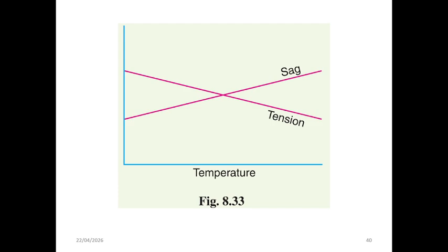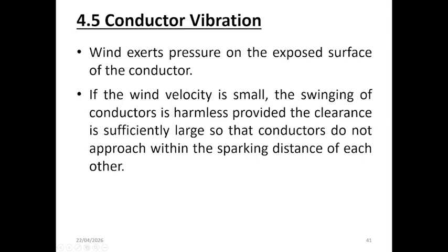So stringing charts are extremely useful for you and the technician, as they provide a practical reference to ensure that conductors are installed with the correct tension and sag under varying environmental conditions, thereby maintaining safety, reliability, and proper ground clearance.